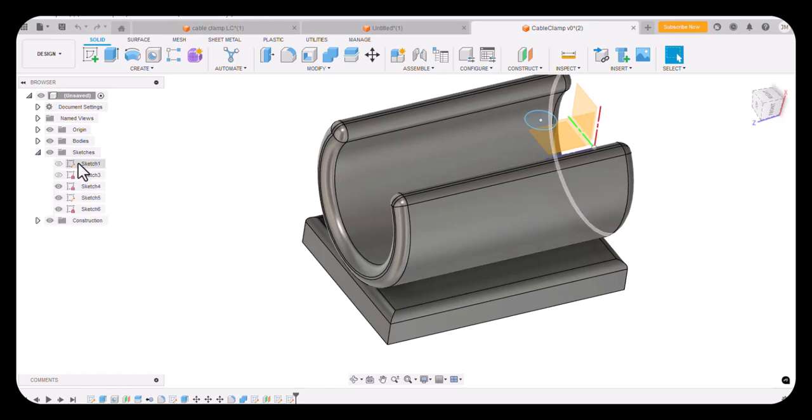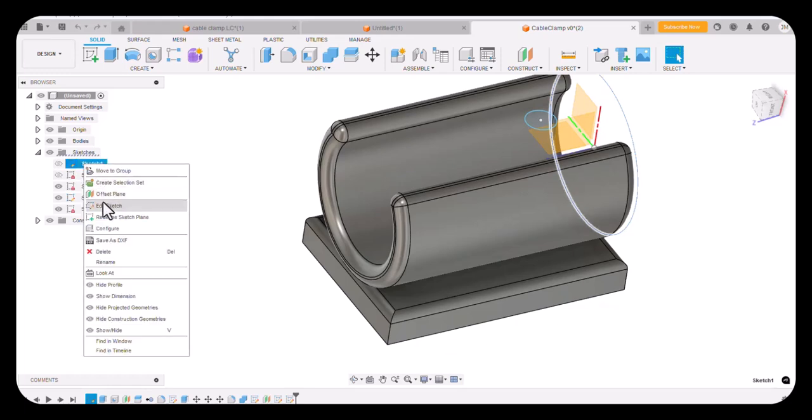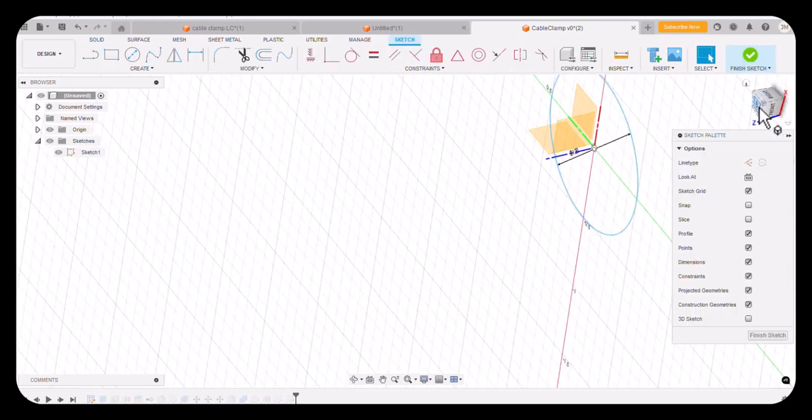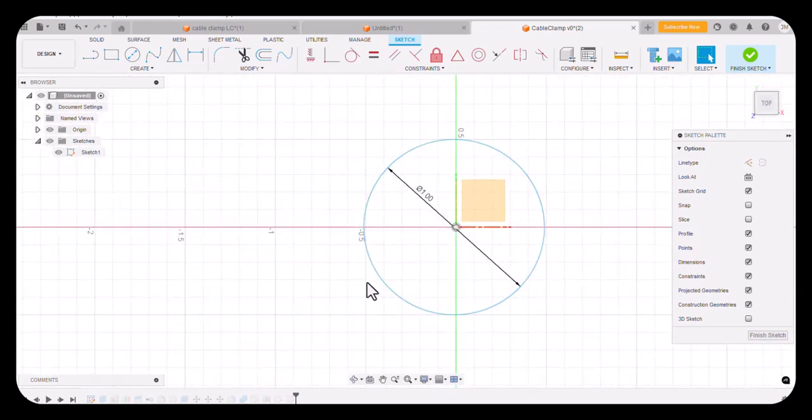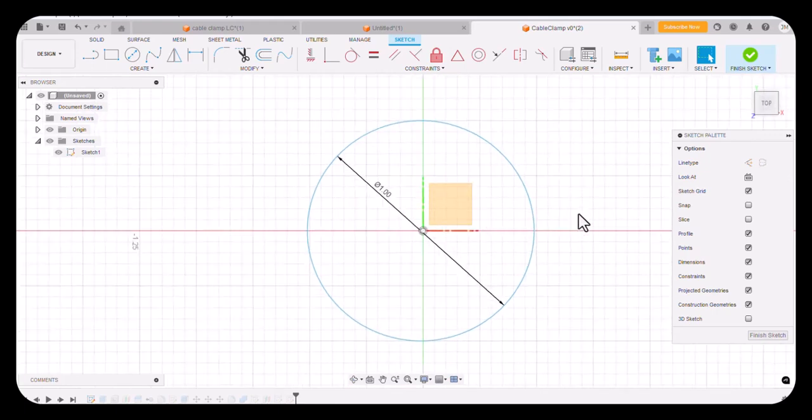And so if I go to the first sketch and I edit that sketch, first of all, I notice that it doesn't have this red lock symbol on here. That indicates that the sketch is not fully defined. When I edit that sketch, I see that I have a 1-inch circle placed at the origin, but the circle hasn't turned black. That means it isn't fully defined.